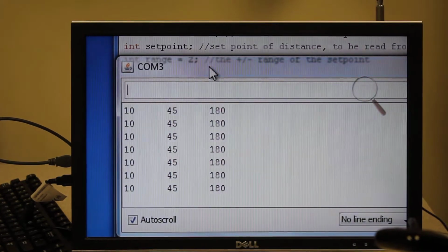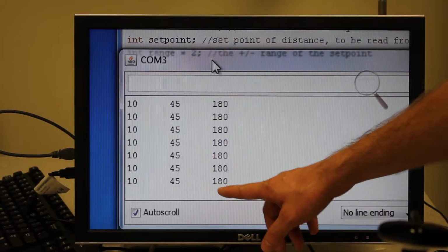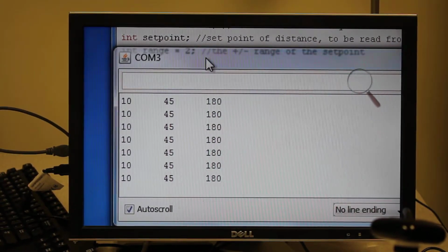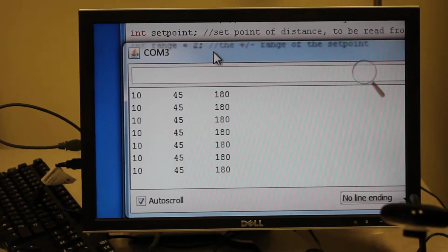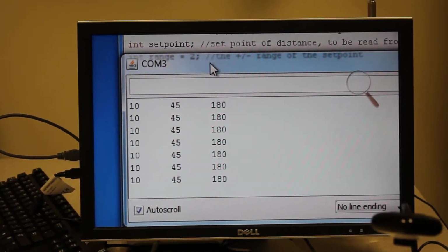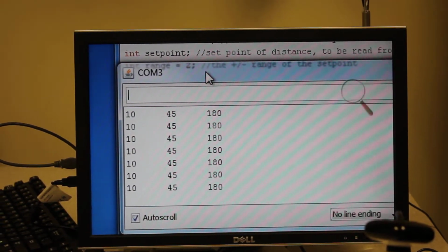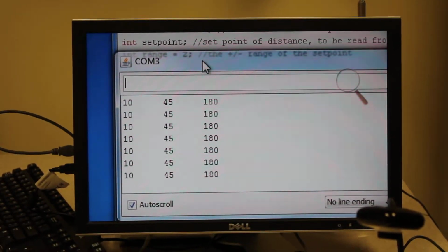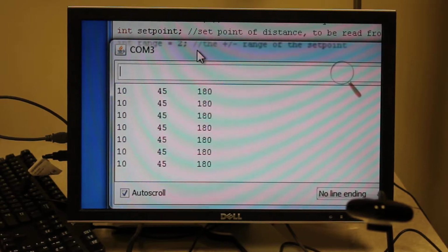And then the 180 is the current decimal value of the 8-bit register being sent out to the digital analog converter. I chose 180 as a value because during testing that was the value that just started to turn the fan up. So rather than wait to get from 0 to 180, we went ahead and started at 180.